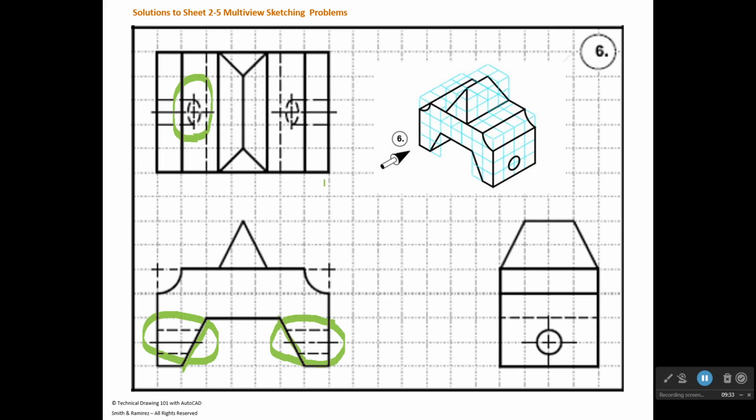All right, and I think that's the first time we've had to deal with that. So here's how you figure out the size of the ellipse. First off, the ellipse, it's 1 unit wide because the hole is 1 unit wide. So that's how wide it is on the y-axis. But to know where the ellipse begins and ends, you would project from where the hole intersects on the inclined plane and project up.